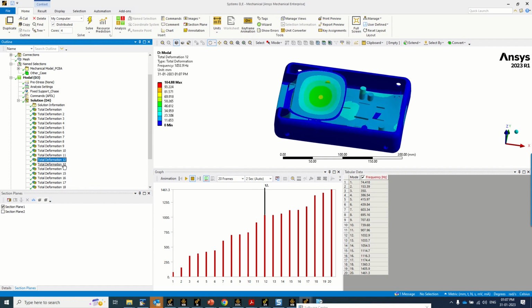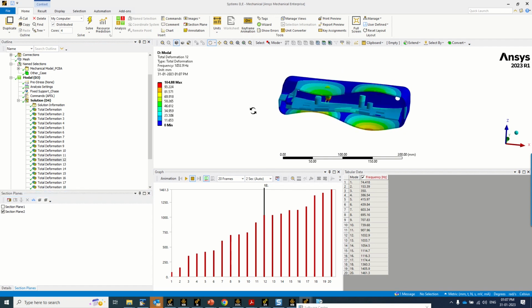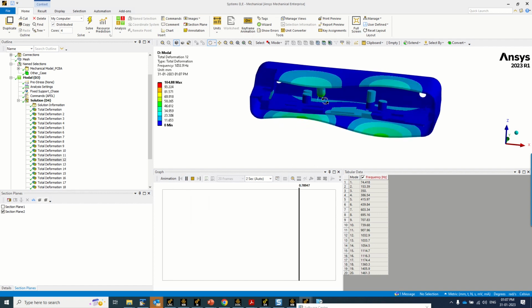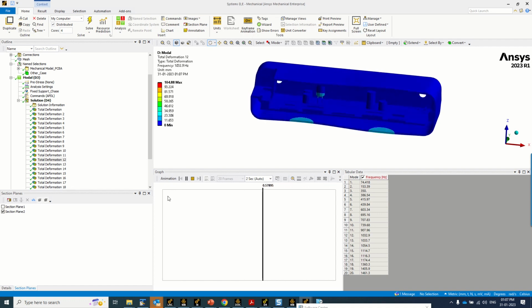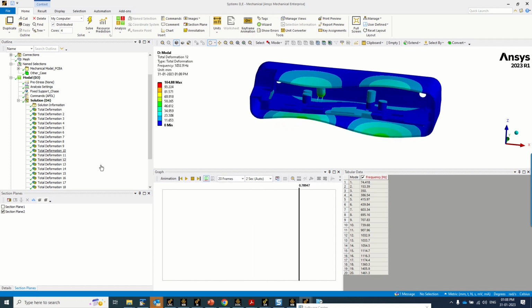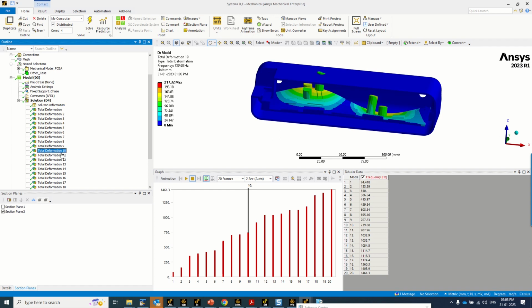You can see this is a combined mode between the board, both the board components and the casing. It's a combined mode, all these things put together. But one interesting point to see here is that our random vibration excitation comes only up to 1000 Hz, up to this mode 907. This mode is 1032. It's a little away from the excitation range of frequencies.